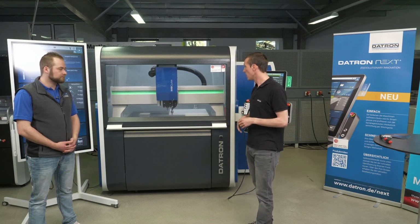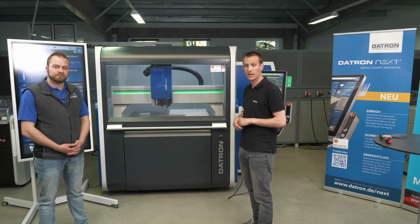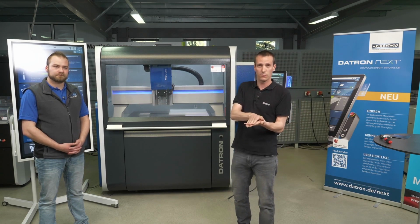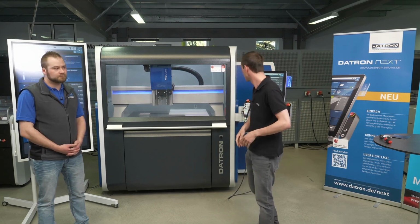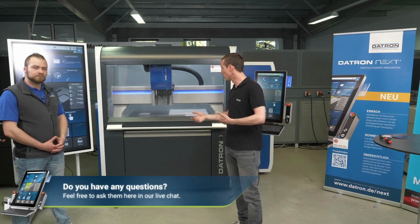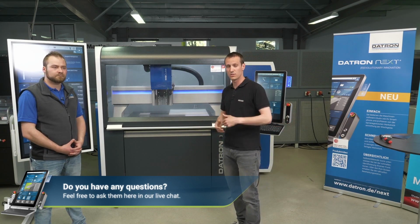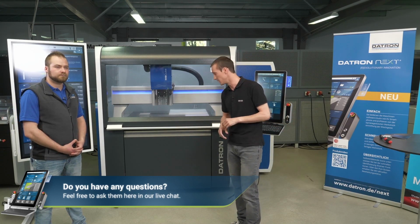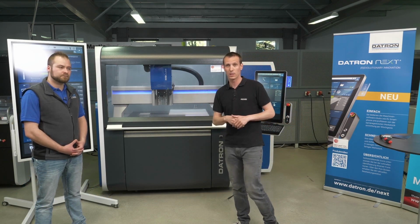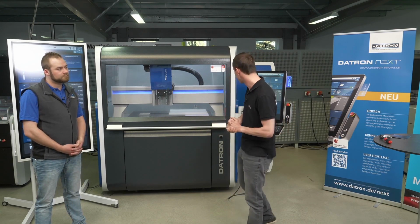So it's also getting the right angle if it's a little bit shifted and rotated around some axis, which is a big thing when it comes to a two-side operation, and you want the first side to match with the second, or the second with the first. So that is an extremely important function to have, and you don't have to deal with mechanical stops and dial gauges to bring the part perfectly aligned to the machine system. So that's it. All I did was swipe over the display a little bit, and my zero point is all set.